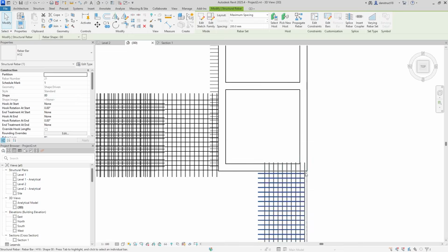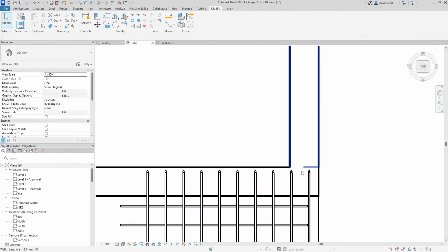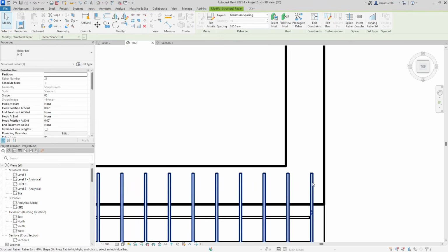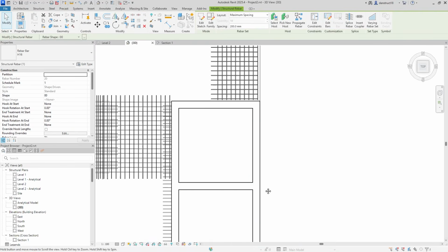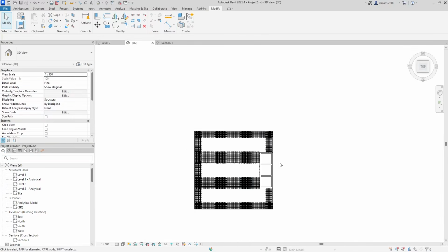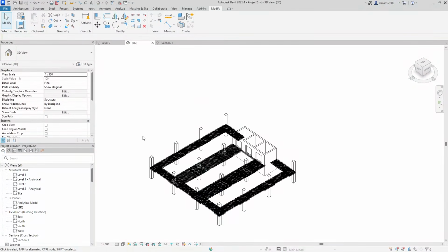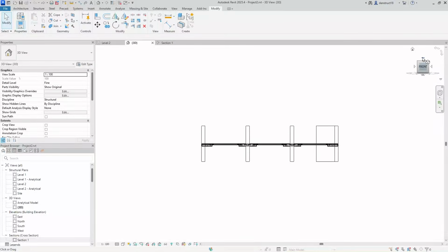Great. Then I'll do the same thing in this direction. Drag it here and drag it here. There we go. Don't want it to be too close to the support. Or rather, let's pull it inside here. Good. So the U-bar will be where the support will be. So good. That's what we did here. Alright, good. So you can see we've been able to place the corner column strip bars. Now let's go ahead and place the column strip reinforcement in this direction and in this direction. I'll go ahead and switch here to the top view.